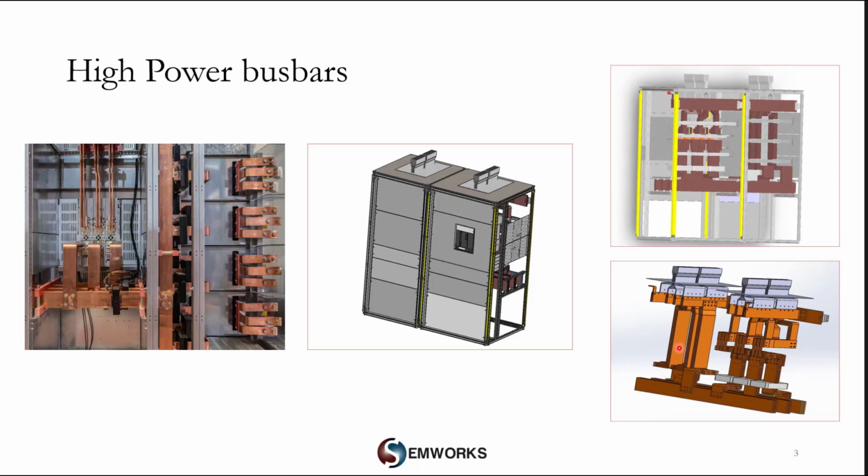They are made usually of copper or aluminum in tubular, rectangular, or flat shapes depending on their application and the amount of current that will be transmitted. The issues that need to be addressed in the design of busbar systems include temperature rise due to energy losses, energy efficiency and lifetime cost, short circuit currents, stresses and protections, and maintenance.